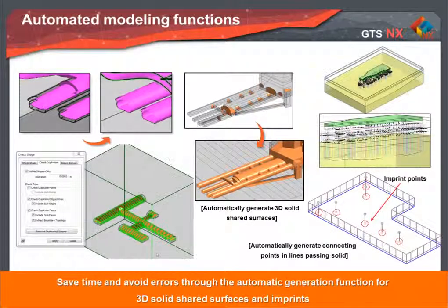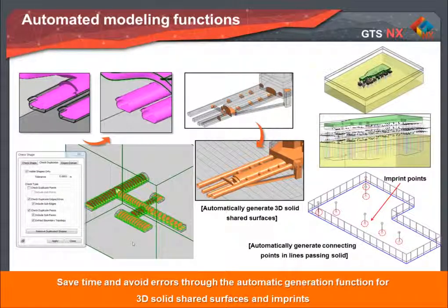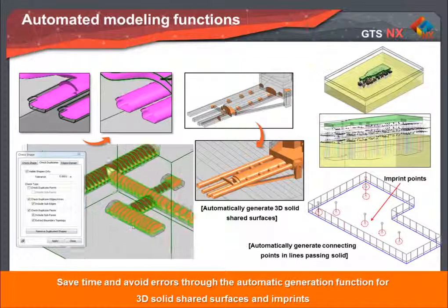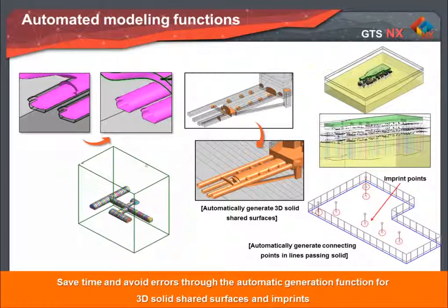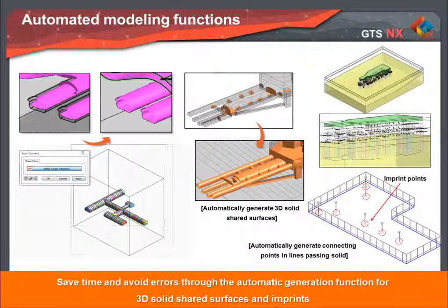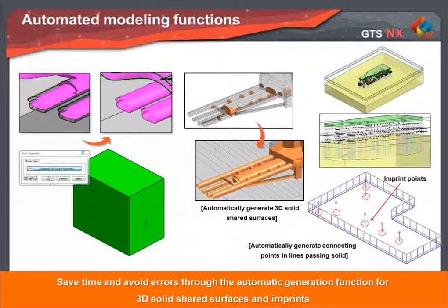Now, moving on to the next features, I would like to introduce the auto-generation of co-phase between adjacent solids. Using this feature, we can automatically generate shared faces between adjacent solids, guarantee nodal connectivity after meshing, and reduce 3D modeling time significantly.